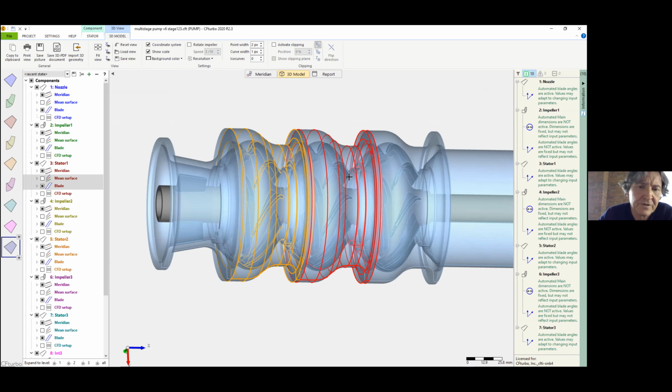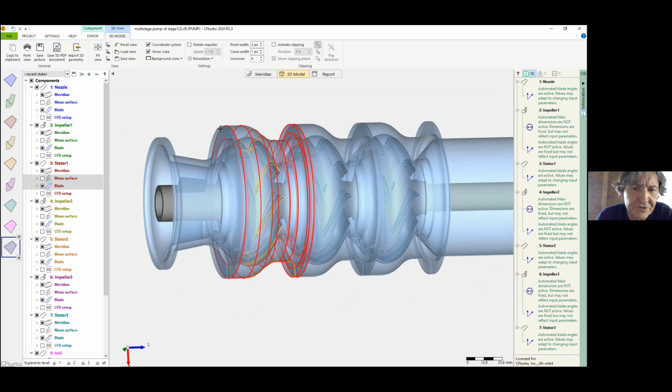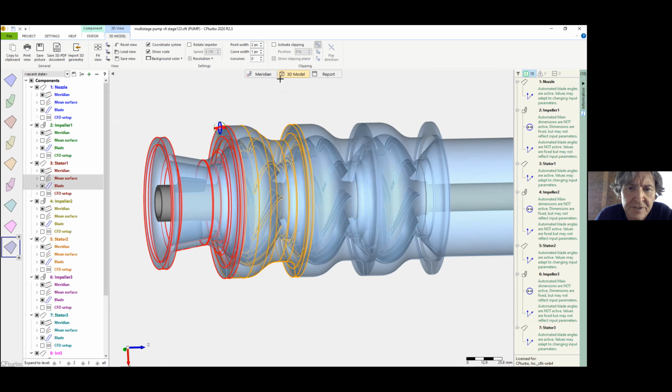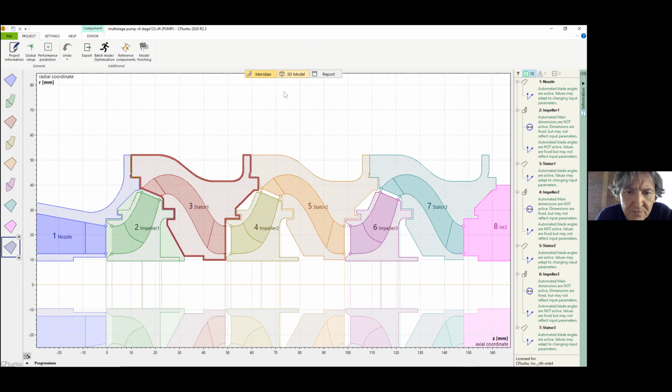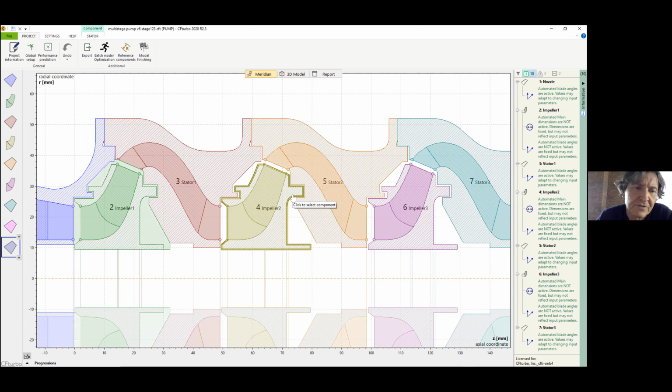What we can do here is so-called model finishings, and also then closing the gaps to build here the leakage flows. So we have to decide, do we want to have a simulation with a leakage flow or without? So in the first part of the webinar, we talk about only the models without the leakage flow, and in the second one, we will come up with the leakage flow.